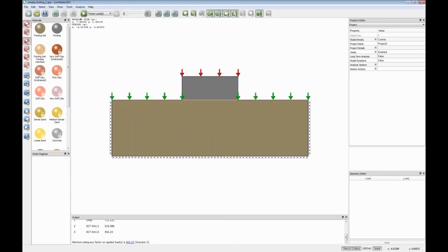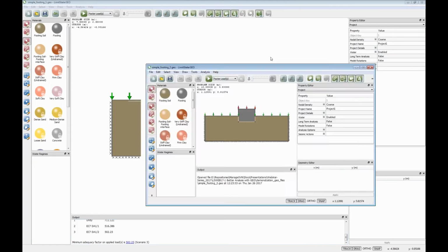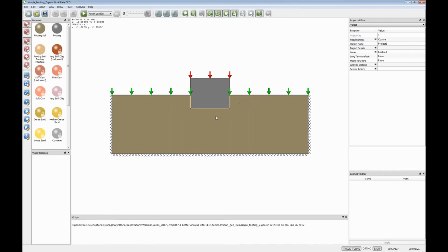What we'll do now is just look at a slightly different variant. This sort of analysis you could easily do using Terzaghi's bearing capacity theorems and formulae, and you don't really need a piece of software to do that. But you may come across situations where you have a foundation that's buried. It may be that you've got layered soil, or the soil is changing its strength with depth. You may have a slightly asymmetric problem, and then it's much harder to use those standard formulae.